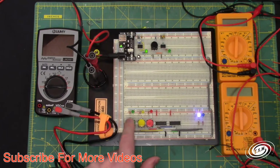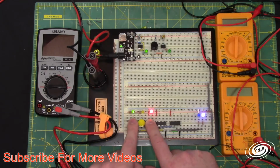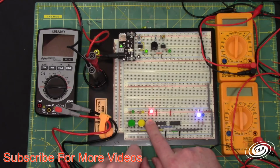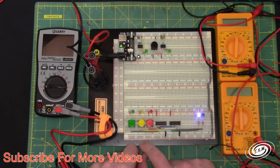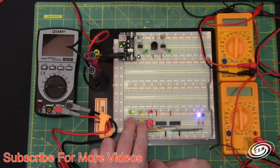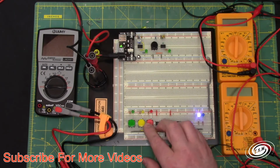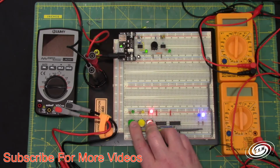So if I press the set or reset, nothing happens. I have to press the enable, and then I can reset it, and I can set it, reset, set. But if enable is not pressed, no matter what comes through on the set and reset lines, nothing happens until that enable is pressed, and then I can do something.